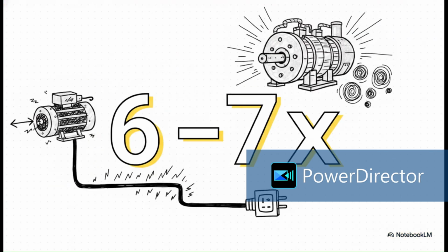Okay, part 3, controlling HT starting current. You see, solving the insulation cost is really only half the battle. We also have this universal baseline fact for electric motors. The absolute second you hit start, a motor will draw 6 to 7 times its normal full load current.